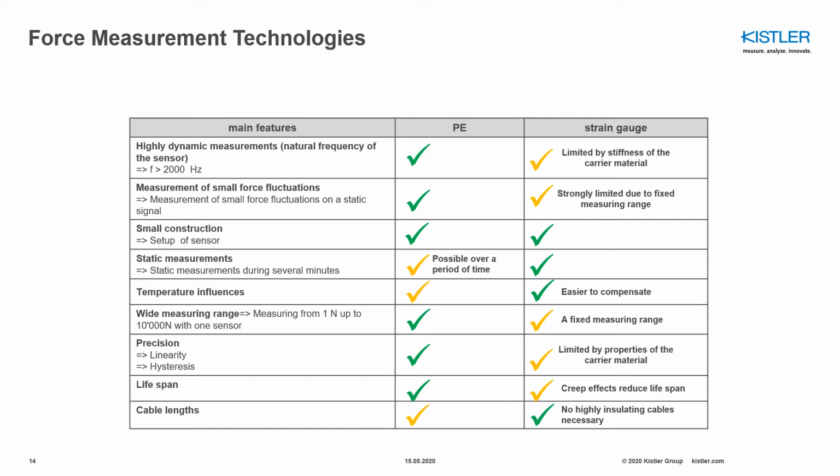On the other hand, strain gauges enable us to perform more static measurements over longer times, during several minutes. The temperature influence is easier to compensate, and we don't need highly insulating cables as we need for the piezoelectric sensors.